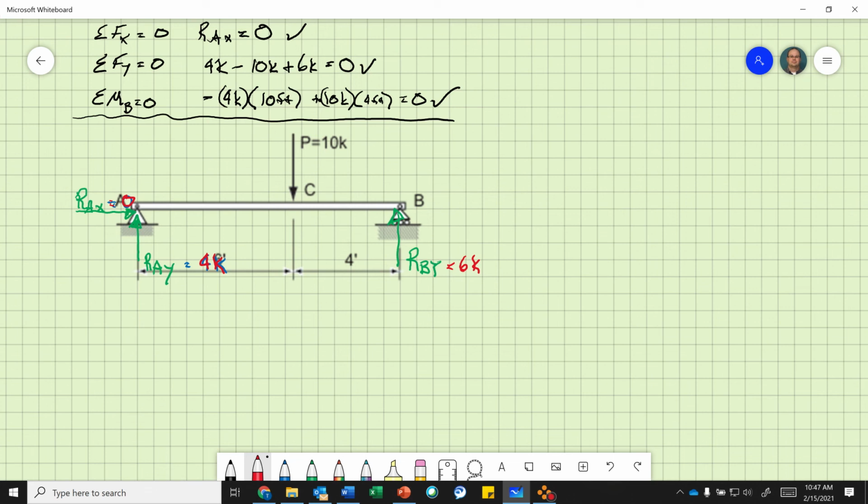For an example, we may want to find it right at 6 feet to the right. So let me erase so we can see the dimensions there. Okay. Or sometimes, as plumbers and HVAC people do, they'll cut holes in your joists or your beams, and then you want to figure out the shear and moment at those points, to determine if we're not going to break the beam. So that's why in pre-engineered joists they have pre-knockouts. That's important for that planning, so those get designed.